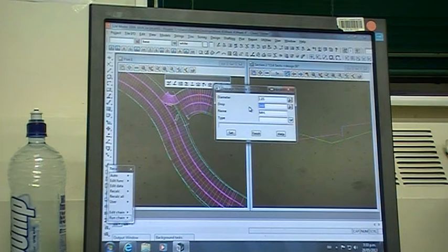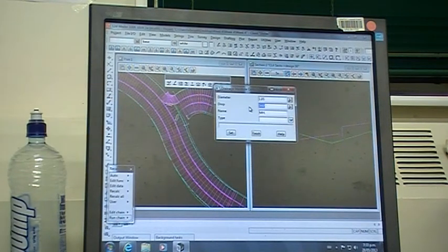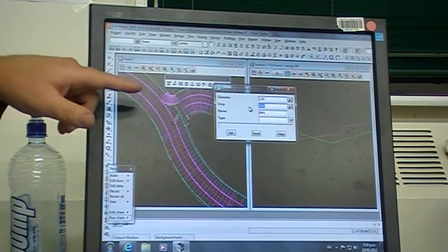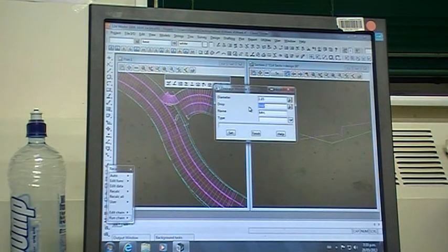Obviously if you've got a line at as flat a grade as you can lay, so 1% or just below, the more manholes it goes through, the more of those 20-30 mils add up. You can sometimes get yourself into a bit of trouble with cover. And again, you'll see this as we get into it, but it's extremely hard for a drain layer to come along and plaster the benching if it's only 20 mils across the entire manhole, okay? So from a practical point of view, to make it easy for them, I set that to 50 mils.